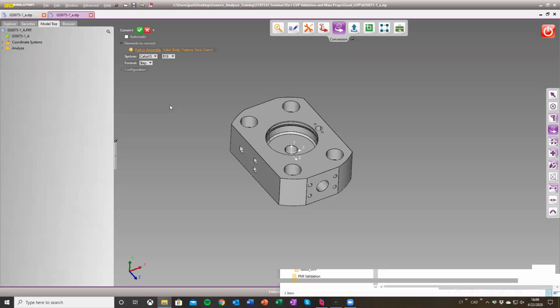The second advantage is that Core Technology has the ability to heal the geometry based on a specific tolerance. If you're writing it out from CATIA, it's written out thinking that you're also going to open it up in CATIA, when the truth is that you're using it for other downstream applications. So the model is not healed from a geometric standpoint or a topology standpoint. Core Technology will heal that model to create consistency on downstream applications so that you don't end up having imprecisions or a non-solid model. Hopefully that answers your question.